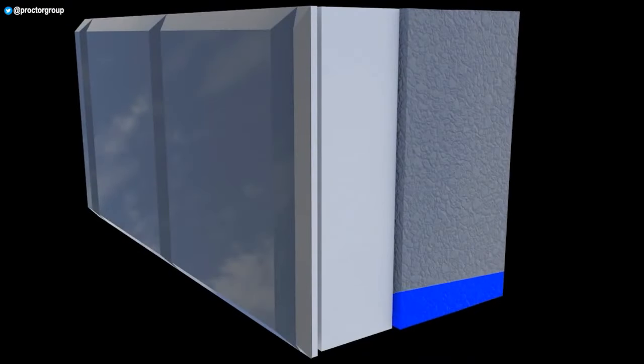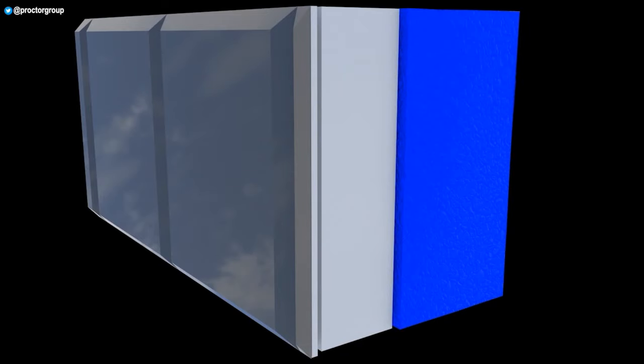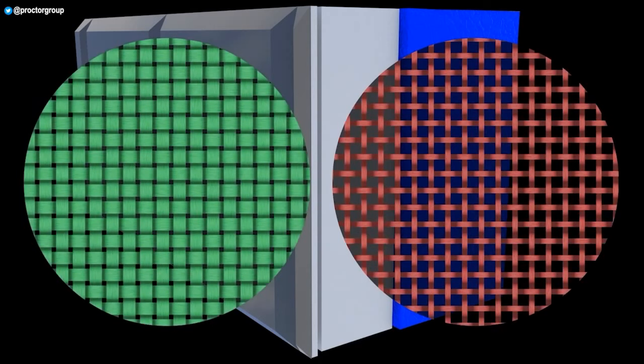Moisture can also be transported by capillary action. This describes the ability of water to travel up through a building or material against the flow of gravity, like for example how water will wick up through a paper towel following the direction of the fibres. Capillary action works best with smaller pores rather than larger holes. For example, the fine pores found in brickwork or concrete provide an excellent mechanism to be used for this wicking action.